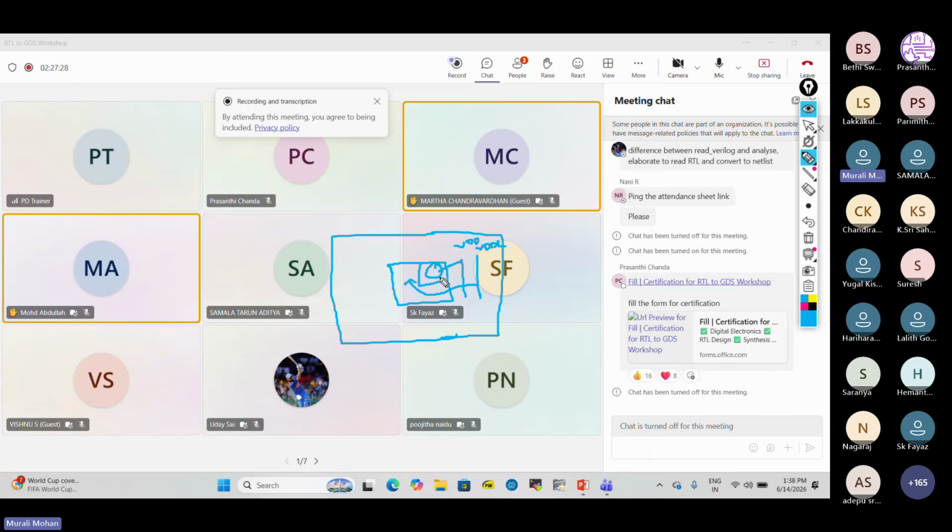At that moment, what will happen? You write the power plan script in such a way that it routes up to here only. It is not supposed to enter into this domain. It has a separate domain name. As per the domain name you write, you give the extensions as well as the blockages you want to use. So with the help of the blockage, this metal layer won't enter into this one. Understood what I'm telling?